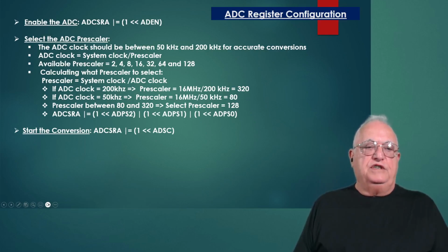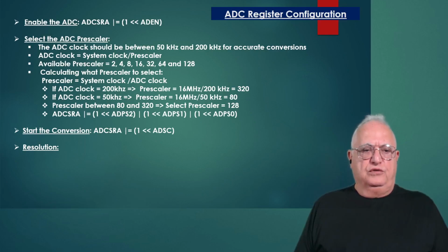Next, we have a register to start the conversion. That would be putting a 1 in the ADSC bit, which belongs to the ADCSRA register. Next, we have resolution.